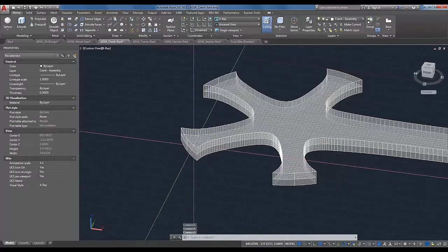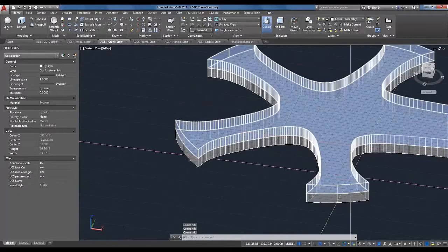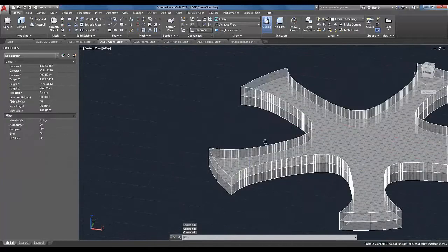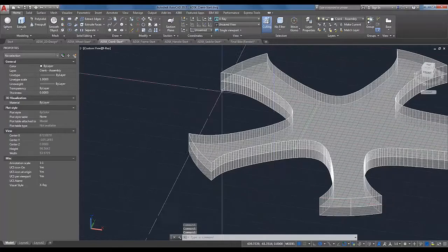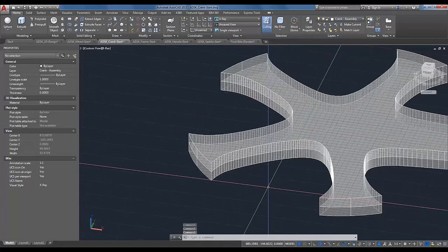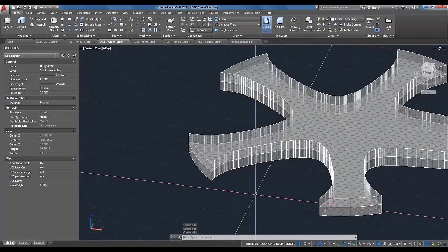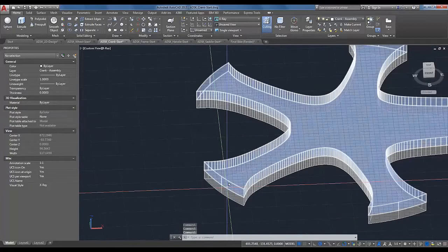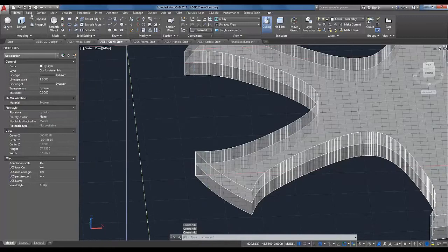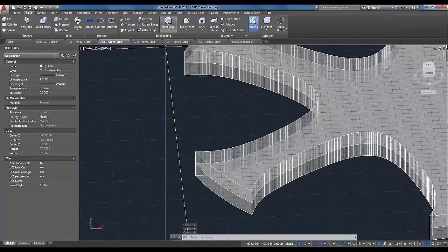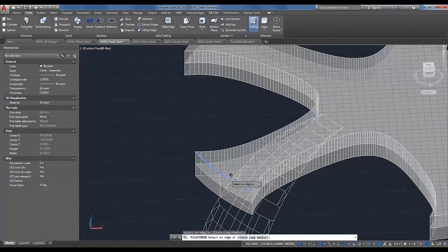And if I put this on my bike right now, I'm going to be presented with some very, very sharp edges. And if I'm pedaling along, you know, probably not the best idea. It just seems like a hazard waiting to happen. What I can do is if I go back to the solid guy here, see this fillet command? Well, a fillet edge. I'm going to select that, and I'm going to grab the top edge of this thing. And down here I have a couple of options, chain, loop, and radius.